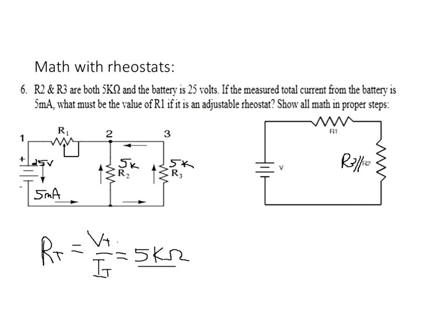Now think to yourself, how do I find the parallel resistance of a 5K in parallel with a 5K? Do the math for that. How do you do that? Come on, how would you solve two resistors in parallel with each other? Well, wouldn't that be the reciprocal of 5K plus the reciprocal of 5K equals, take the reciprocal? Well, what would that turn out to be? Do that math. Well, as it turns out, that's going to be 2.5K.